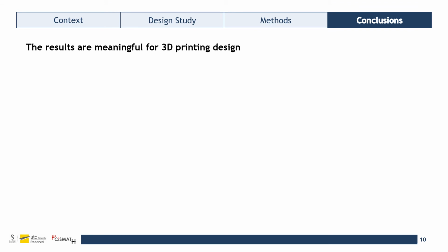As I promised at the beginning of the presentation, there is a relevance of this research for the design of 3D printed continuous fiber composites. But therefore, I would like to summarize the findings and then make the link to 3D printing. The first finding of the conducted research is the demonstration that it is possible to study the influence of input variability at a low computational cost. This refers to only two finite element analyses needed by the CGSM.